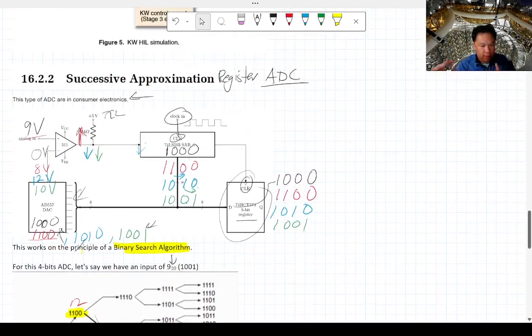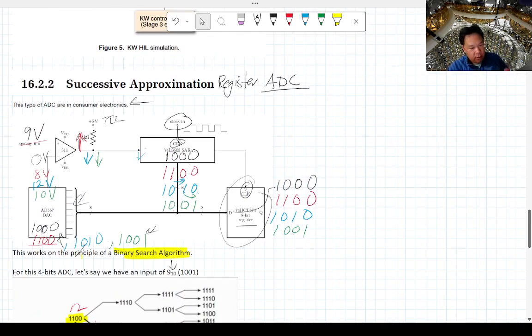But be a little careful. This information gets transferred over multiple things. Each guess takes a few steps. First of all, the comparator has to do it. That information gets sent into these logic gates, which take 1 or 2 cycles. So let's just count that as 1. Then it has to register that number into your register, and then send that data over to your DAC, the digital analog converter, and that has to get recorded there. Then the next step is that it has to send that information back to the input comparator. So every guess takes about 5 cycles.